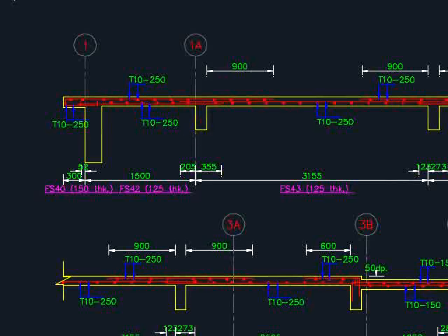Normally, we don't need to provide double layer of reinforcement bar in the slab. What is essential is you need to have bottom reinforcement bar at the midspan, and you need to have top reinforcement bar on top of the support. And when they are lapping, you need to clearly indicate the lapping length.